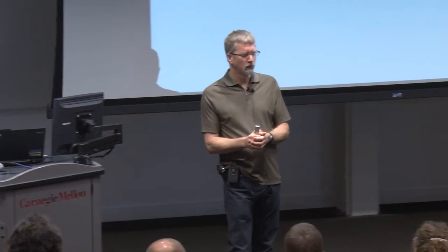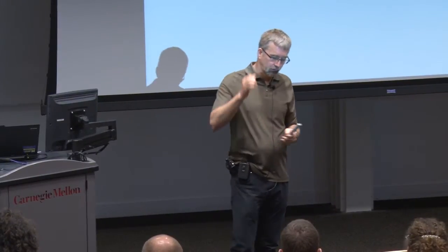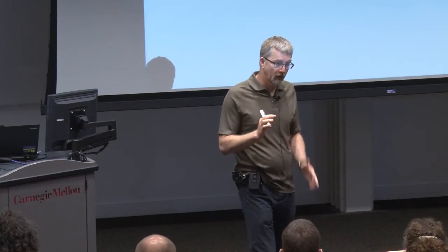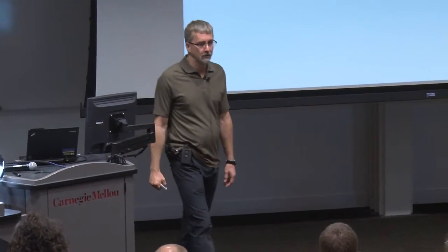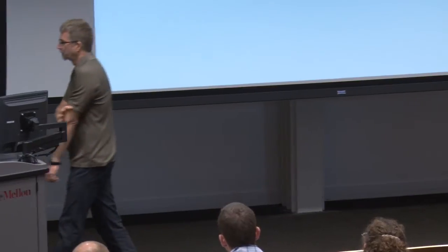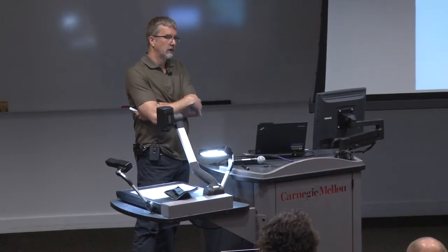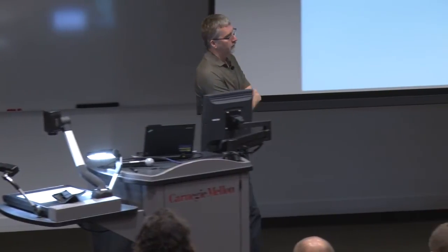I'm having a little bit of bad foot placement from bad tracking control in the hips and stuff. And then I'm not transitioning properly. I'm not stopping this one from being swing phase and making it start taking the load and then transitioning. So I'm having problems there. So I think the question is, can I do more robust design of my desired trajectories? Yeah, okay. So the answer is I think I can. My simulations say that I shouldn't have to be so uncertain about when to transition on gait.